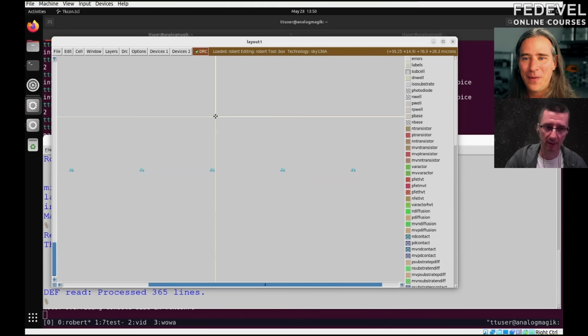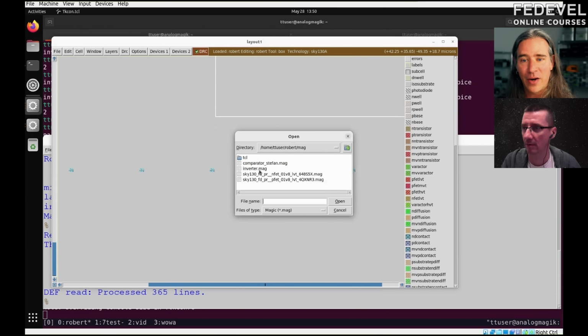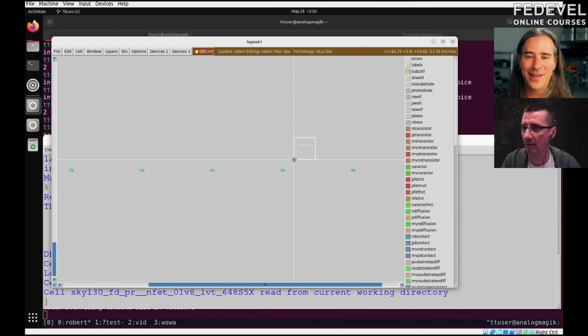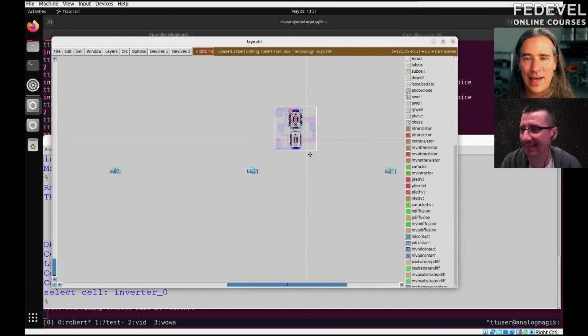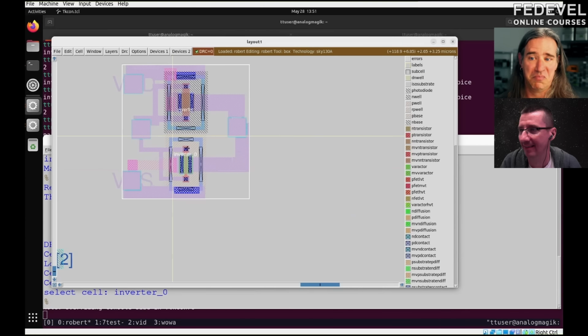Now we have to import our inverter here. So all I have to do now is cell place instance, because we created this cell and we have our inverter. It's very, very tiny. This would be a sad project, but if I can look inside here, bloop, there's our inverter. And all I have to do now is connect in to one of these pins, out to one of those pins, and VDD and VSS to power rails. We could do it, but let's say we did, okay?